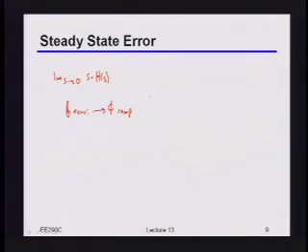Now, just to get the dimensions right, it's going to be some frequency offset divided by s squared, because that frequency offset tells you how quickly the phase accumulates. But that is indeed going to be your phase ramp. Okay? So now if that's the phase ramp, then as we said before, let's just pretend the CDR is basically a first order loop.